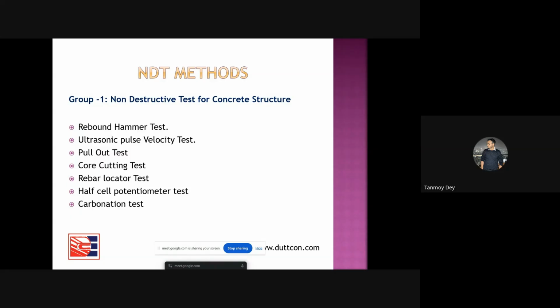So now sound has entered the object. It goes through the entire length, and when it comes out of the object, once again it finds two media, the object and the air. Once again, a part will be reflected and a part will be refracted. Now you want the reflection. A part is reflected back. When reflected back, we take another probe to pick up the response of the reflected sound.